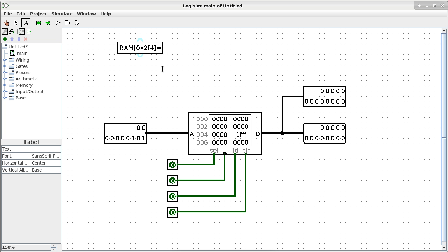And the new content at that location is, I can specify up to 13 bits. So let's specify 0x FED, okay? All right, so this is what I want to do. The question is, how do we do it? Well, it looks like the first thing we need to do is to specify that location. So now the question is, which number do I present to the A port? Do I present 2F4 to the A port, or do I present FED as a hexadecimal number to the A port? Exactly, 2F4, okay? Because using the array indexing notation, that is how you select which element in the array to change or to access. So in this case, that's what we need to do.